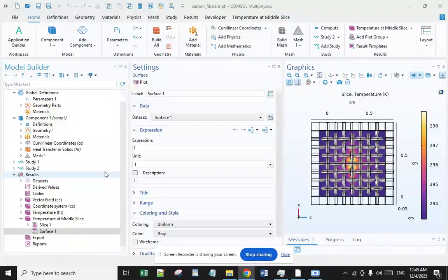Beyond these studies, there have been no further developments in the techniques for measuring the thermal conductivity of textiles in composite materials. The use of infrared or IR thermal mapping may be a better method to focus on the heat transfer inside the sample area only to determine its thermal conductivity, and then move to the interface to determine the interface contact resistance.